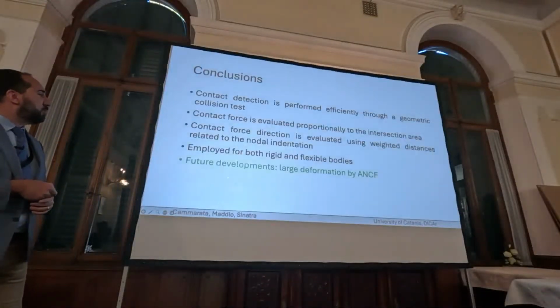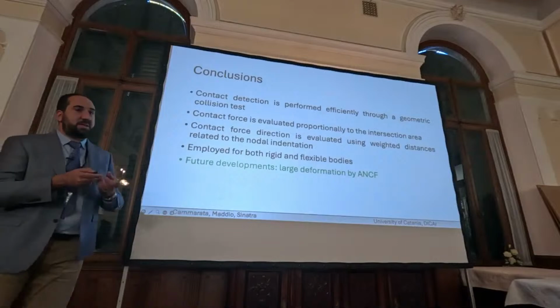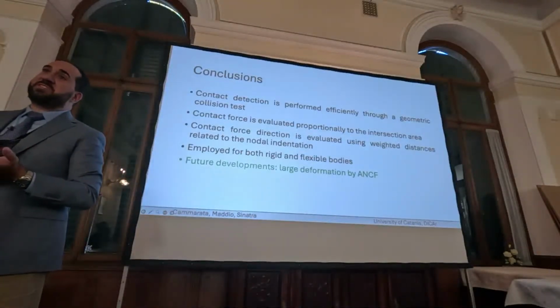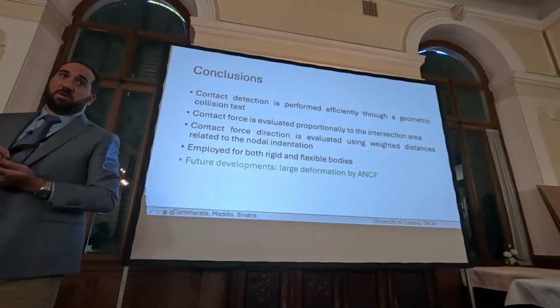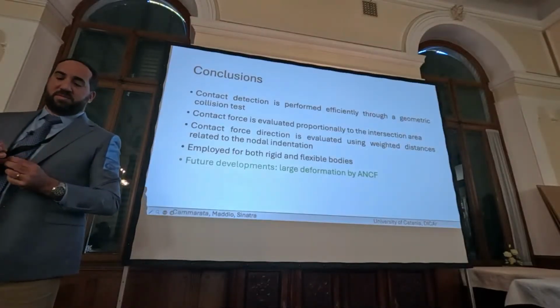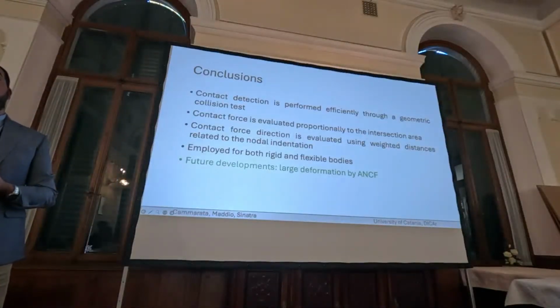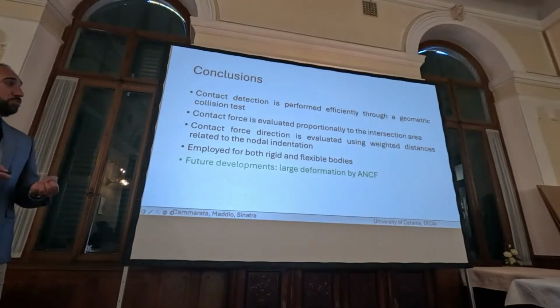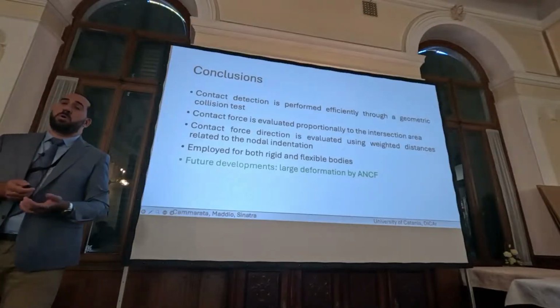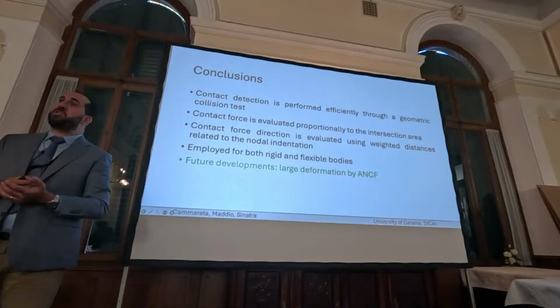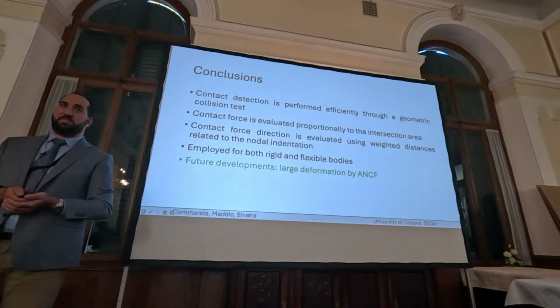And I conclude with the future developments. We want to extend to large deformations. We already have the tangent stiffness matrix of the contact, so we obtained the tangent stiffness matrix, but we have to change from the floating frame of reference to another method, the absolute nodal coordinate formulation. The absolute nodal coordinate formulation is able to work with large deformation and large displacement at the same time. Thank you.